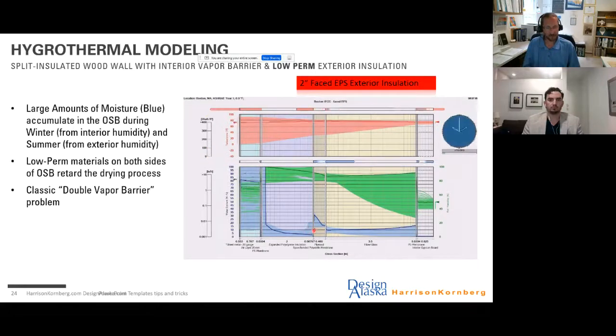But we see specifically what's happening in this climate in this model is the plywood layer. It's actually OSB. We see water accumulating there, and it accumulates sometimes because there's a driving rain event from the outside. Well, you'll see a little peak like we just saw here, but it's also accumulating from that vapor-laden air from the inside that exfiltrates to the outside in the winter. That's what we're seeing, a little bit of that now. And you might be asking, why is this a very unsafe level of water content now?